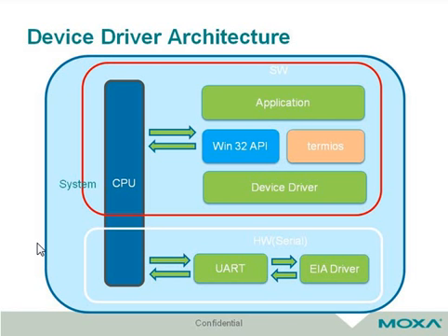We can see three levels in the software part. They are application, API, and device driver. When a serial transmission is being performed, application issues commands to driver through API. So the driver can understand what user wants to do, and then driver controls UART directly. So we can say a driver is a bridge between API and the hardware.